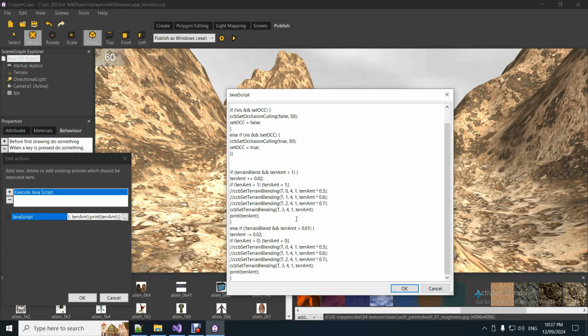Now this number 1 here is the adjustment that applies to where the 2 textures blend. Only where there's 2 textures connected together, the blending of those 2 textures. If you're using a single update on one of the textures, it's better if you put 0.5 there, it'll look a lot better. If you don't, it'll have a sharp cut off between where one texture starts and another one ends. But this will blend it in a little bit better at 0.5, so you'll see that.